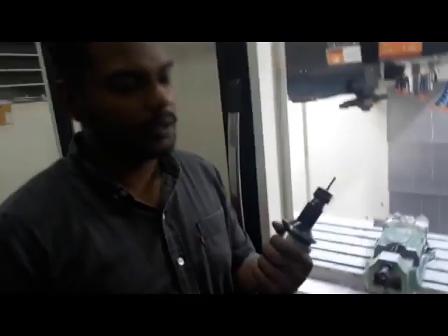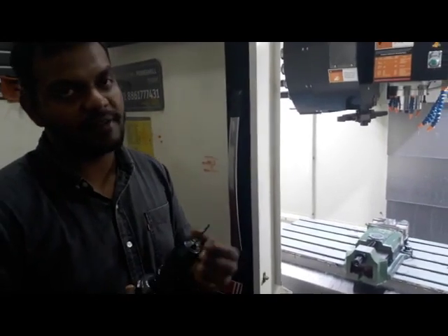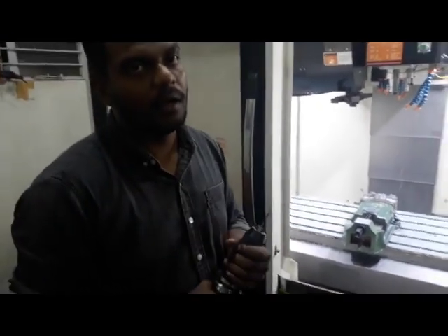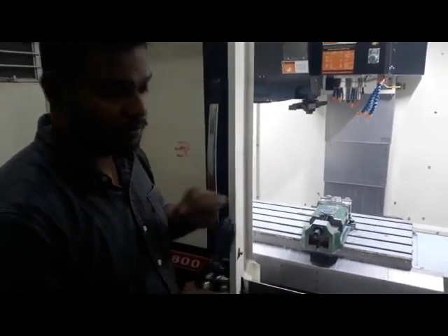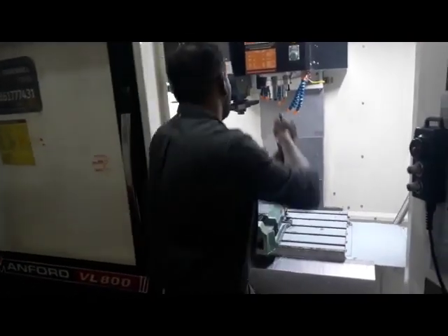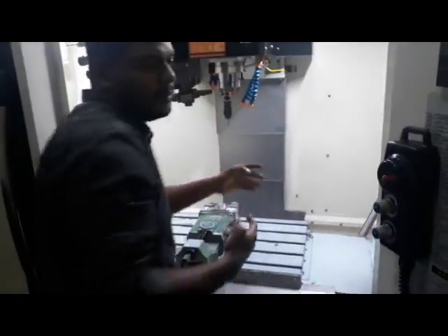So I've taken out the 4 flat end mill, and I'm going to put the 3.5mm drill. This is a carbide drill, so because I have a carbide drill, I do not have to use a pilot hole. So I'm going to go ahead with this operation. This is the 5th operation. And I'm going to follow the same procedure.